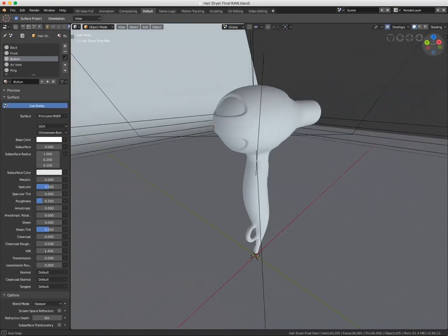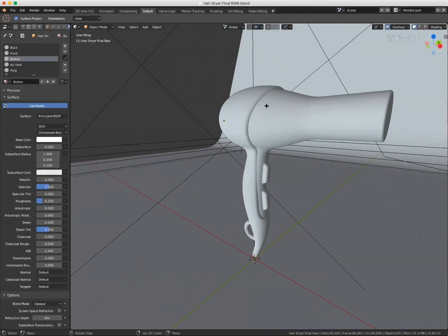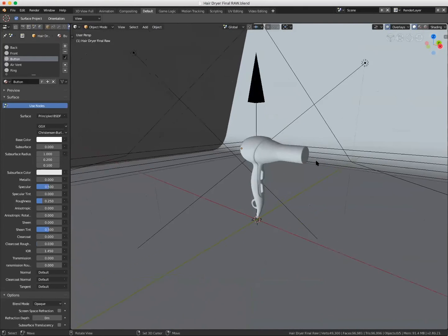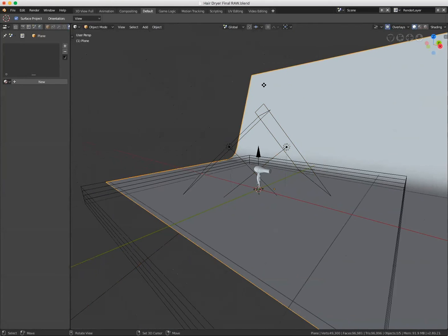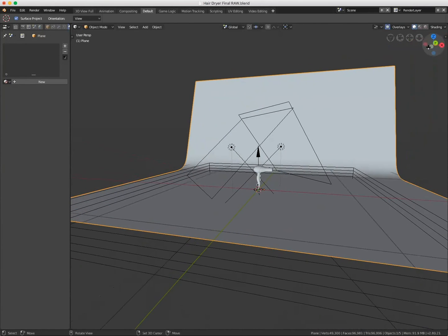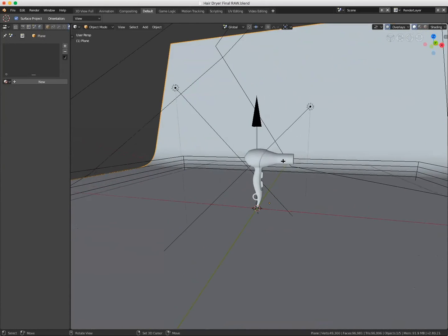And it's free. That's really nice. Here is the hair dryer. When I zoom out a little bit, for those who are not familiar with it, these two objects I'm selecting are actually lights, and I have a backdrop. So when I approach product rendering in my courses, I always teach my students first actual photography with a camera and lights, and then we rebuild the way we did a photo exactly in the render software. In this way, quite often, the renderings will look a lot more believable because we're not guessing, we're actually using real-life photography, just digitally.